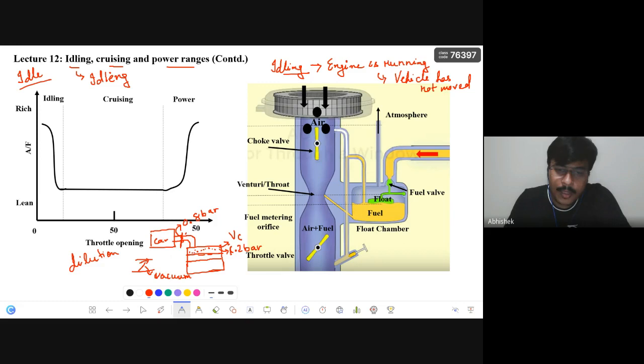So now what will be happening is the exhaust products will be moving here. This is all taking place when the piston is still at the TDC. It has not started to move down, because when it starts to move down, the pressure will reduce here, and then again the fuel will come inside. But just before that, there will be a condition when the pressure at the upstream will be lesser than atmospheric pressure, so the air will be moving out. Sorry, the exhaust products will be moving through this, and that is why the fresh charge is diluted. That is why it is called dilution of charge.